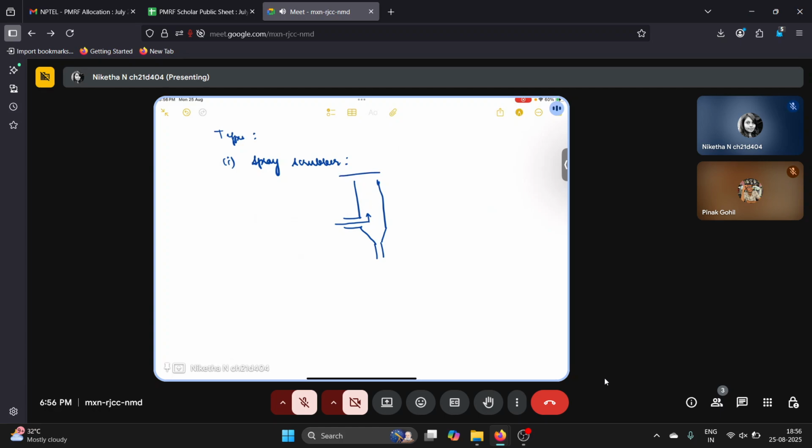And at the top, we have sprinklers. So here the sprinklers are spraying water droplets, and as the air moves up, it will come in contact with the water particles and the dust particles will tend to stick to them. And then the air will move out, and the dust along with the water particles will settle down.